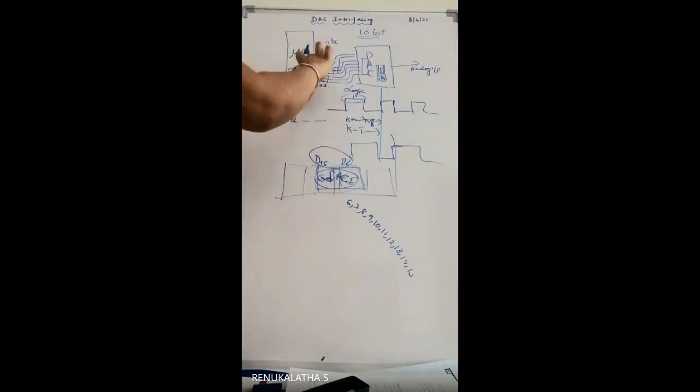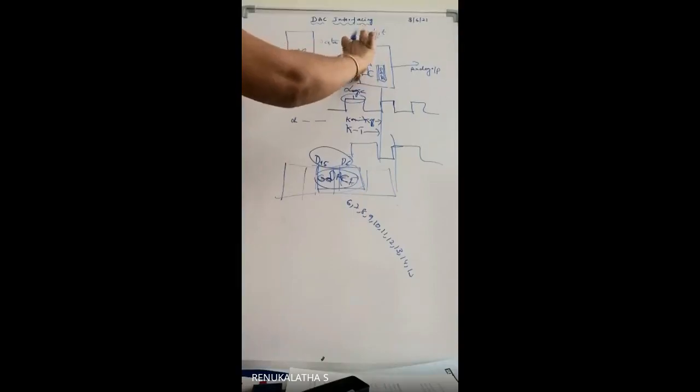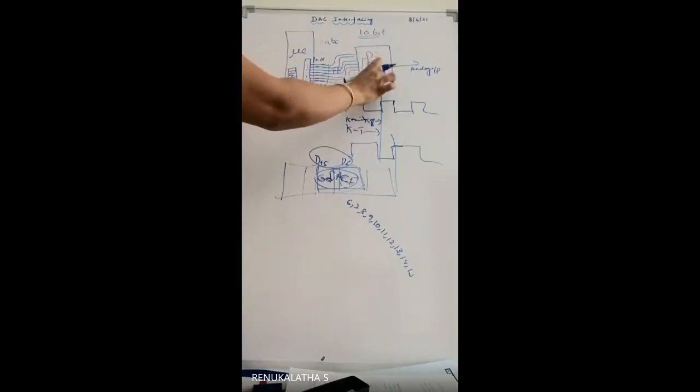As soon as we place the data onto these pins P0.16 to P0.23, the lines are connected to the data lines of the DAC. Later the data present on this data bus will go and sit in the DACR register inside. What is this DACR register?